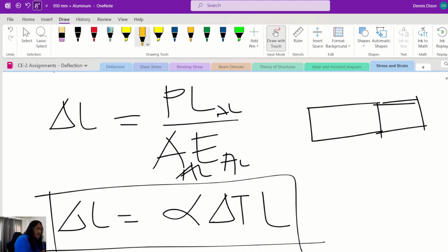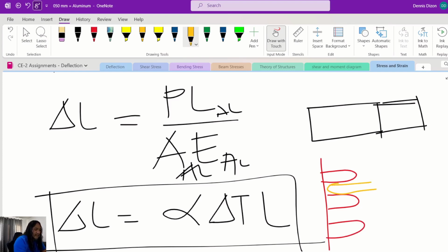Now at the joints, if you notice, there is some kind of finger joint, and then there will be spacing. There's another finger here, and this will move depending on the temperature change.